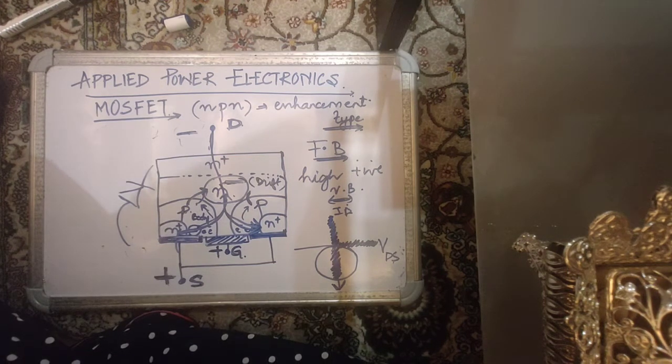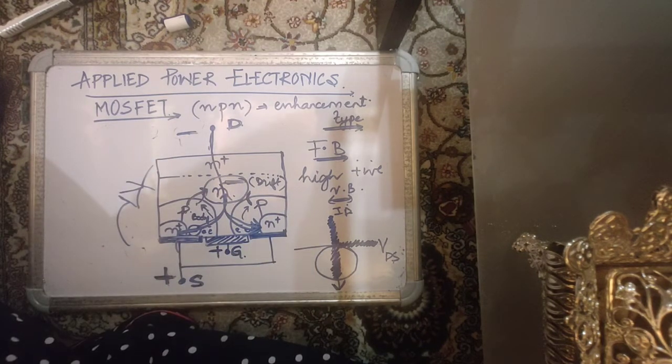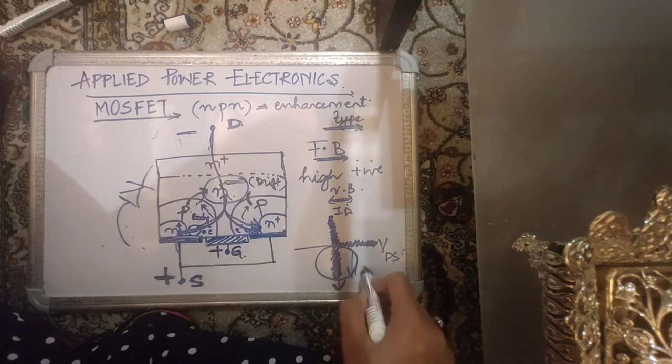For the reverse, the device does not have any reverse blocking capability, because once you reverse bias it, the inherently existing body diode in the device, which is basically inherently present because of the body source short, automatically goes into conduction and starts carrying current in the reverse direction.